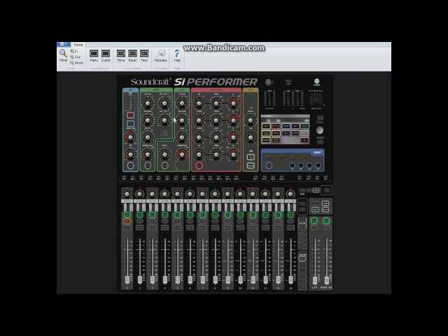All right, the next devices in the chain, these are digital devices in the signal chain, is the gating system. Regarding how to run the gating system, I'm going to recommend referring to the manual for the console that can be found online. Likewise for the compressor. To give it a slight explanation, gating waits for a signal to arrive before it turns on the channel. It helps cut out extraneous noise, also sharpens the sense of attack for different signals, often used for kick drums in a band.